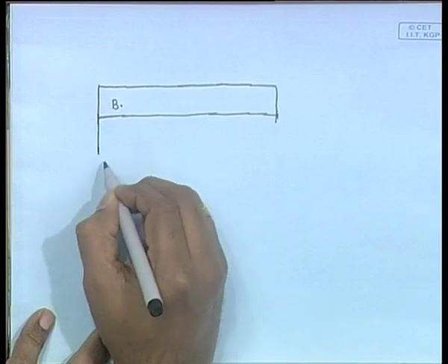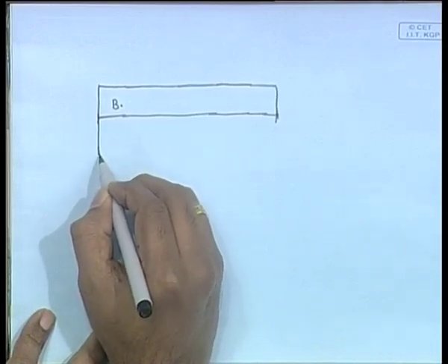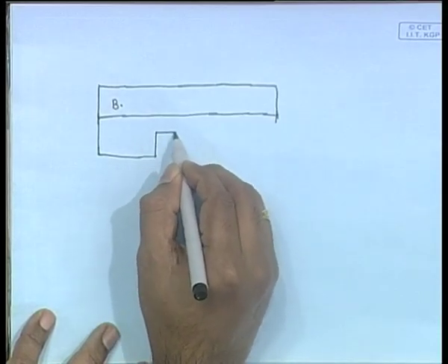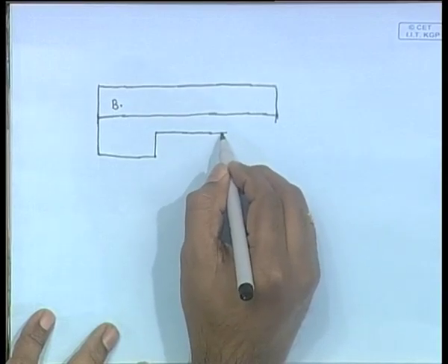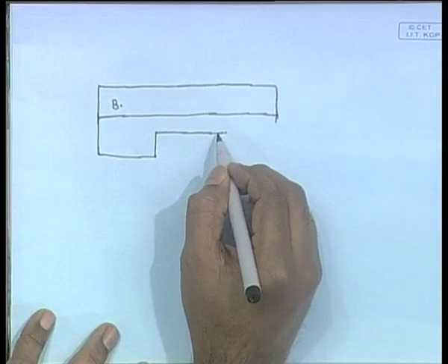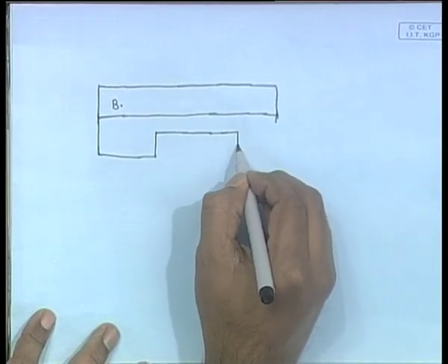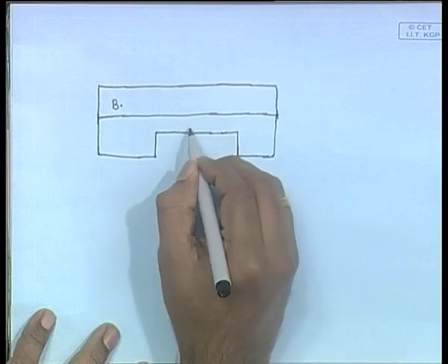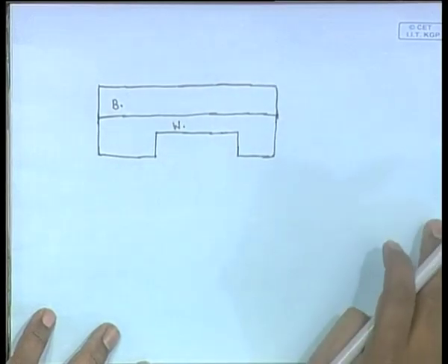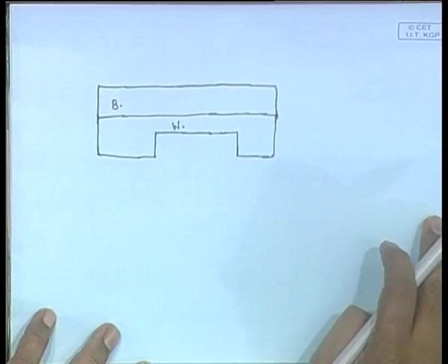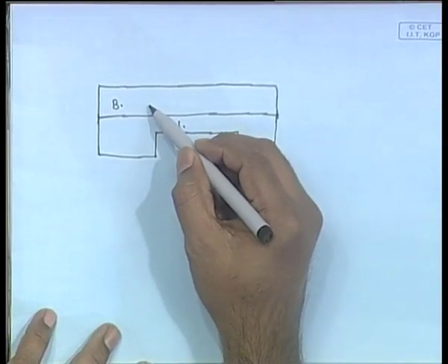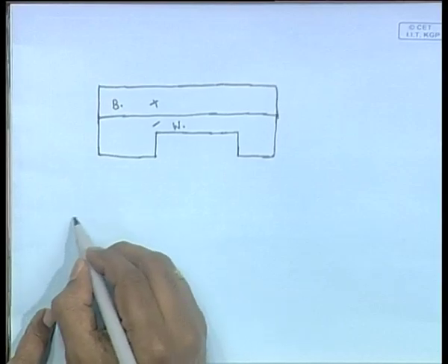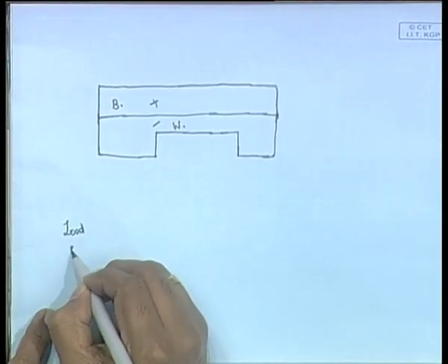In this case what the design says, as is many times seen, is that there is a higher weight here, lesser weight at the center, and slightly higher weight at the forward again. This is the design for this case. So, this is the weight curve, and now the resultant of these two, remember one is positive, one is negative, the resultant of these two gives you your load curve. So, this is called the load curve.